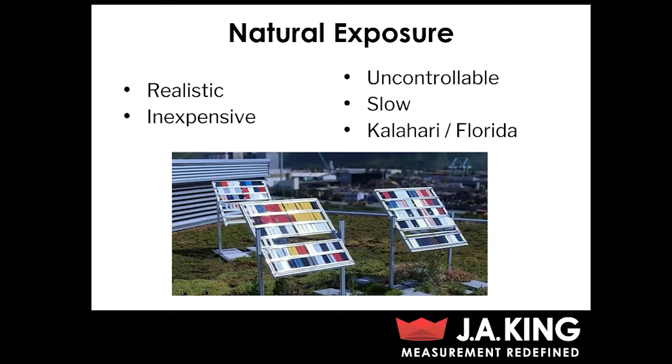But there are some downsides to natural exposure testing too. One of which is that it's uncontrollable. You're really not going to be able to control parameters such as temperature, humidity, and irradiance. Obviously, you can control them somewhat by choosing where you're going to place these parts, what kind of geographic location you're going to put them in. But day to day, those parameters really aren't completely controllable.